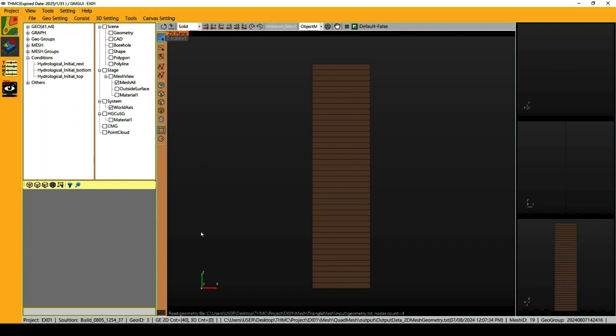In benchmark problem 1, we set a variable boundary condition for the top and a Dirichlet boundary condition for the bottom. First, to set a variable boundary condition for the top, with Add Selection selected on the left side of the window and labeling vertex selected on the upper side of the window, choose Select Edges. To select the element side located at the top of the area of interest, drag to select the top element. Then the window screen appears.